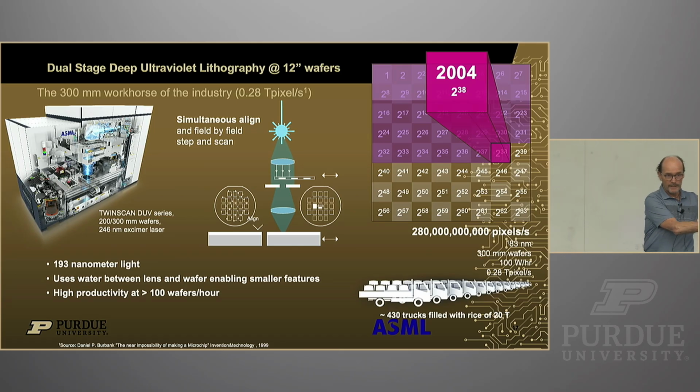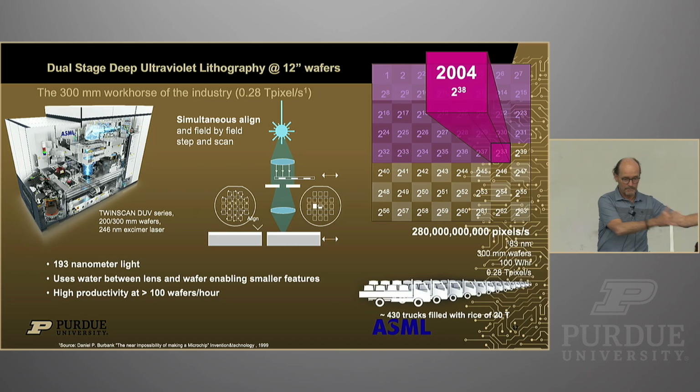So if I have a wafer that I need to work on, I place it on a wafer table. I can do that with an accuracy of mechanically 10, 20, 30 microns. But that next layer needs to land on top of it with nanometer accuracy, right? So first I need to figure out how exactly this wafer landed on this wafer table. We measure alignment marks with a laser. Then when the alignment is done, and I've also measured the whole height map, then I know how I need to expose it.